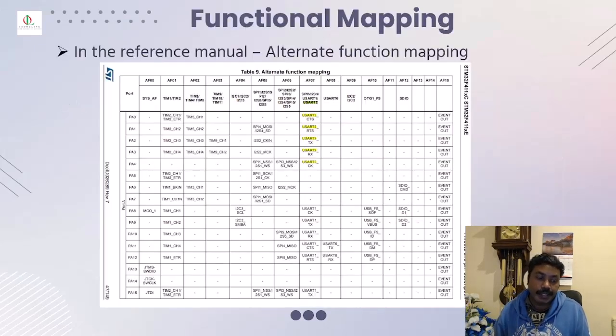We were just learning about alternate functions, how the same pin can be used for different functionality, and how it can be mapped when you want to communicate with the alternate function to the microcontroller. We're learning about port A2 because we're going to use this as the USART2 transmit pin. If you link in this table PA2 and USART2 transmit, it's using AF07, alternate function 07.